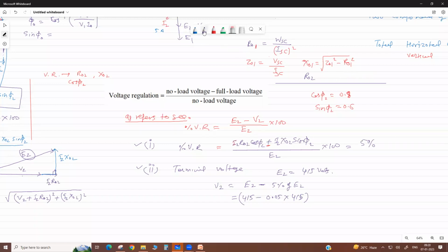When we transfer these, you use K squared, but individually we don't know R1, R2. That's why, if primary side parameters are given, then what do you do? We use the primary side voltage regulation formula.